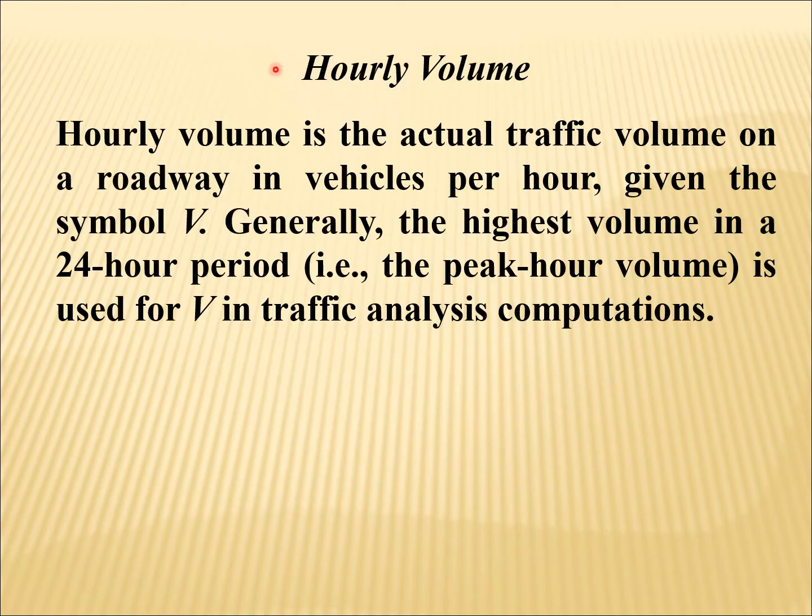Next term, hourly volume. Hourly volume is the actual traffic volume on a roadway in vehicles per hour, given the symbol V. Generally, the highest volume in a 24-hour period, that is the peak hour volume, is used for V in traffic analysis computations.